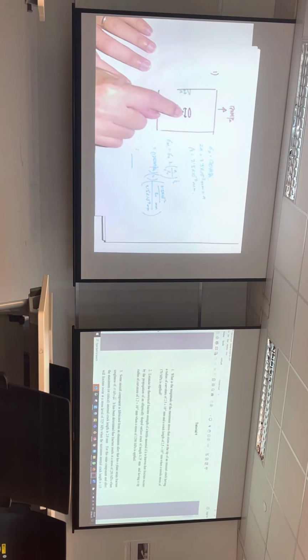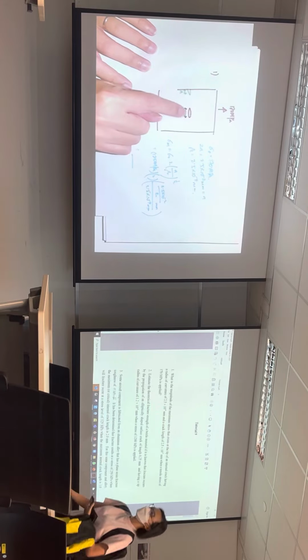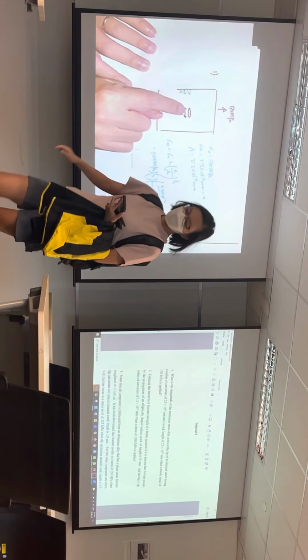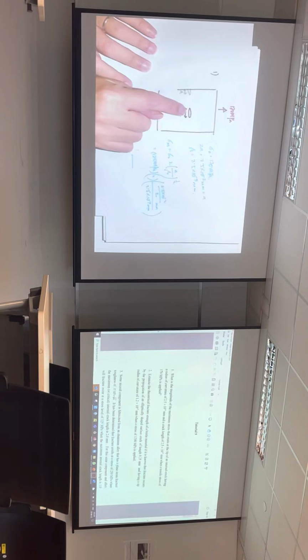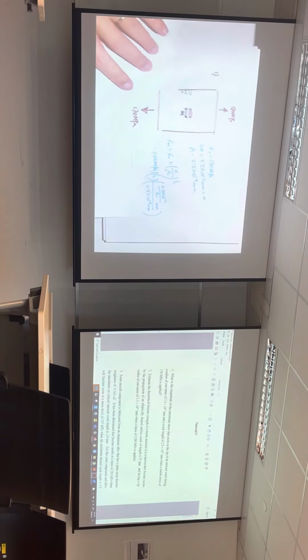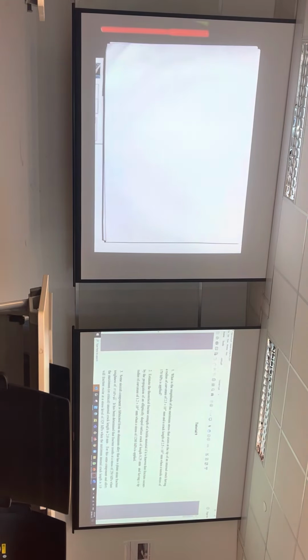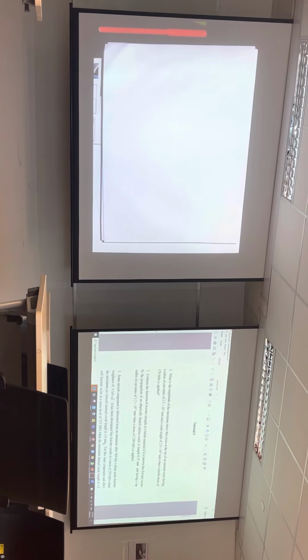Because of this, I hope you also understand the implication of what you can do. Go to engineering, buy a quick fix. Buy time to extend the life of the component, right? You can just drill one hole at the crack tip. So just now, that article is an example of that.